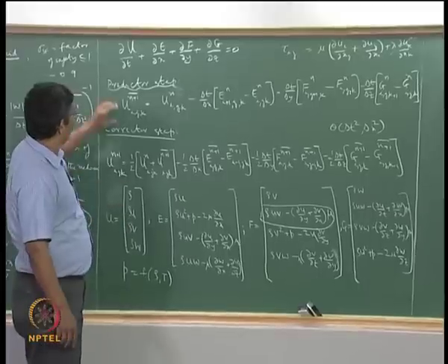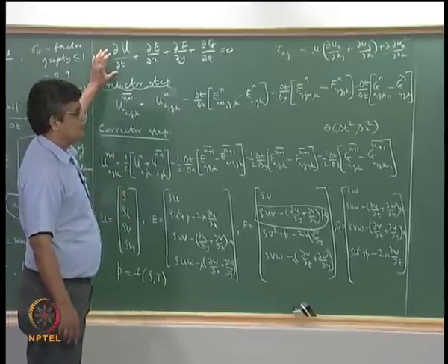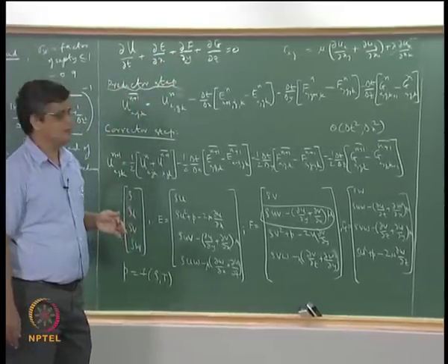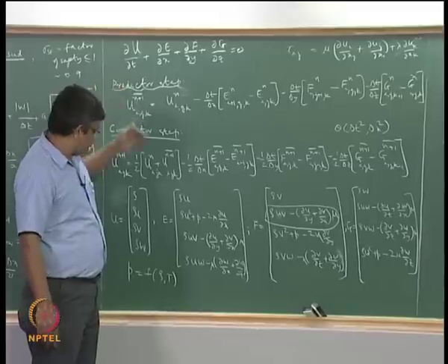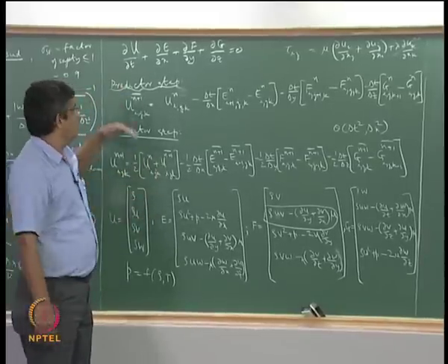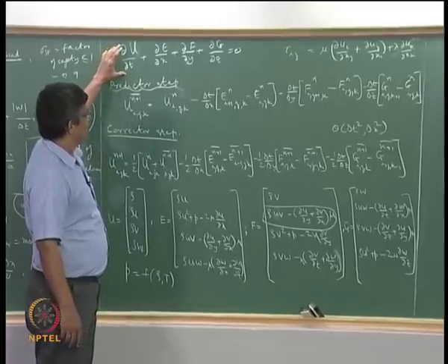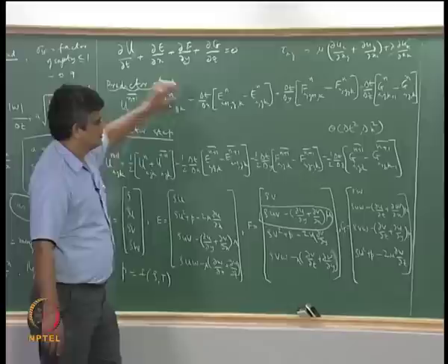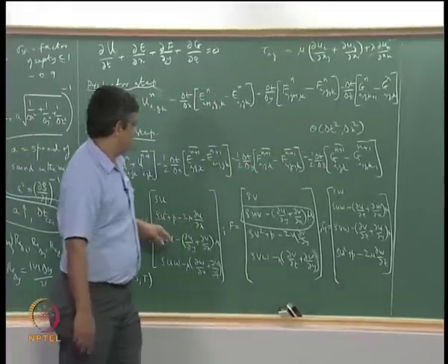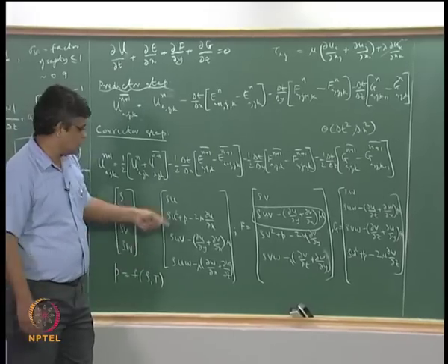Now if you were to solve only the u momentum equation, then your implicit method may give you unconditional stability. But in order to do that, you also need to simultaneously solve the v equation, w equation, and if you make large errors in the evaluation of u because you have used large time steps and therefore you have misrepresented this, then that plays havoc with the values of v and w, which are an integral part of this.